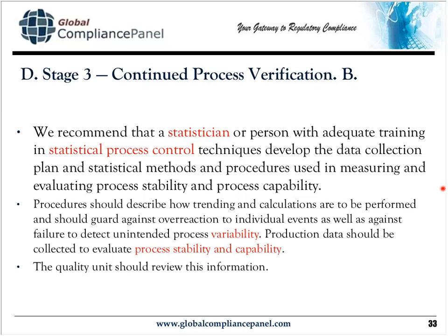The process starts showing that things are going out of trend. You should be looking at your charts at that point, but they're ignored. And everything's routine, no major effects needed or actions needed. And there's a real problem here. So make sure, and for those of you who are supervisors and managers, make sure that these things are reviewed a minimum of once a week.